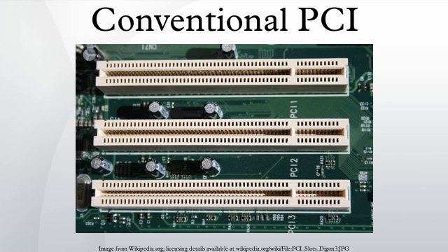Burst addressing: for memory space accesses, the words in a burst may be accessed in several orders. The unnecessary low-order address bits AD[1:0] are used to convey the initiator's requested order. A target which does not support a particular order must terminate the burst after the first word. Some of these orders depend on the cache line size, which is configurable on all PCI devices. If the starting offset within the cache line is 0, all of these modes reduce to the same order.